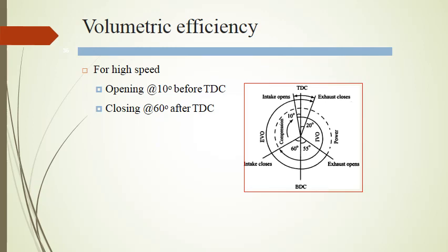For either a low speed or high speed engine operating in its range of speeds, there is some point at which the charge per cylinder per cycle becomes a maximum for a particular valve setting. If the revolutions of the low speed engine increase beyond this point, the intake valve in effect closes too soon and the charge per cylinder per cycle is reduced. If the revolutions of the high-speed engine increase beyond this maximum, the flow may be choked due to fluid friction. These losses can become greater than the benefit of the ram and the charge per cylinder per cycle falls off.